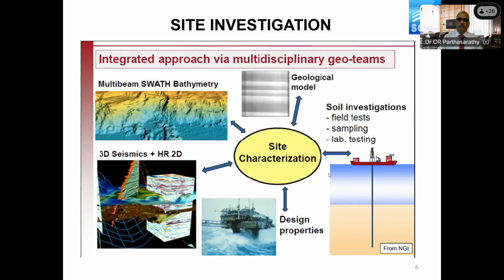So the geophysical survey consists of the bathymetry survey to determine the water depths, and to identify potential hazards like seabed obstructions, existing pipelines, submarine cables, pock marks, buried channels, outcrops, etc., which are detrimental for the safety of the jack-up rigs when they are moved to the location. This geophysical survey will also aid in evaluating the engineering characteristics of the shallow soils.